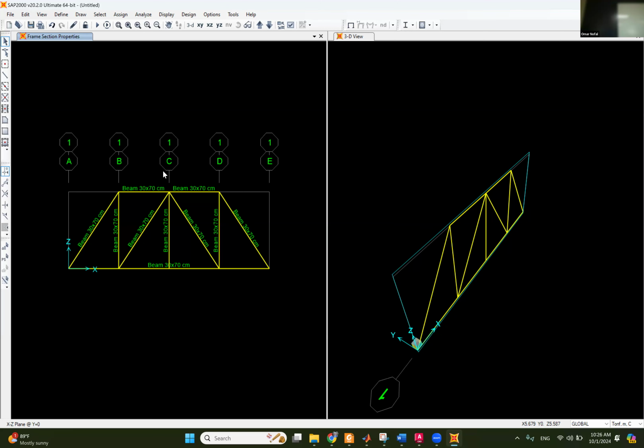So I click on the joint and assign joint thing. Let's see what is the joint thing that we need to assign. So I'm gonna click on this joint. By the way, I want to teach you something. If you click from down to up, it's gonna select anything that is fully inside this box. See, I only clicked on this point. But if I drag from top to bottom, it's gonna also take the members. Can you see?